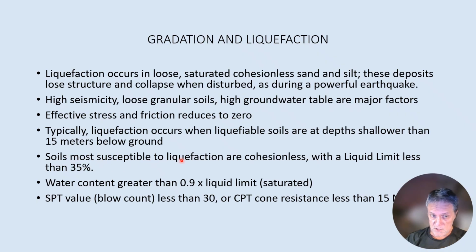Soils most susceptible have very low cohesion with a liquid limit less than 35%. Okay, so it's important to classify soils, especially if your site is sitting above a high water table and you have loose saturated sands down below.